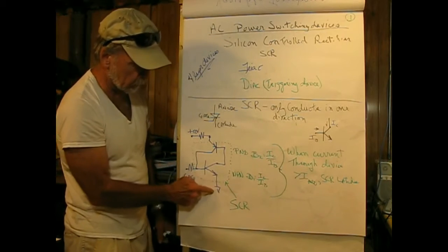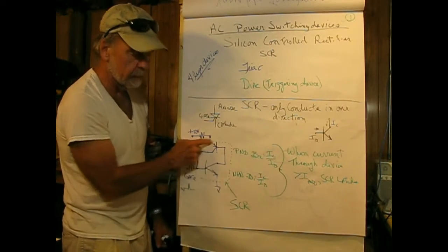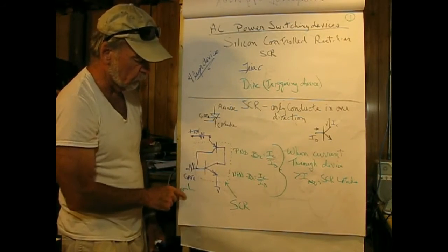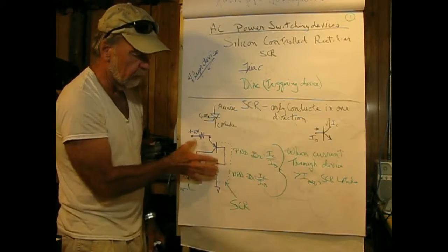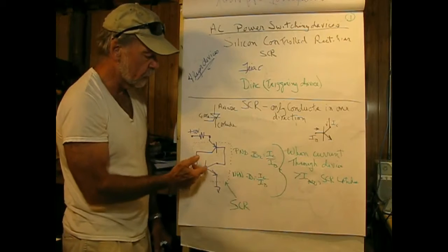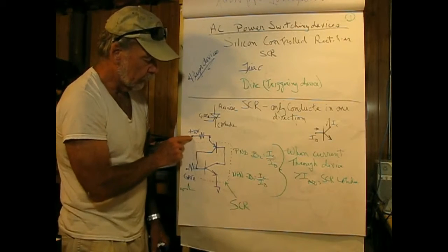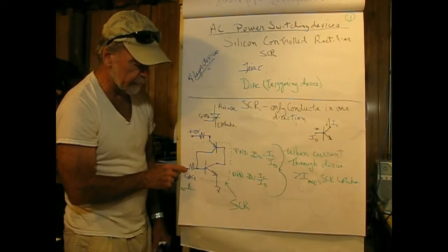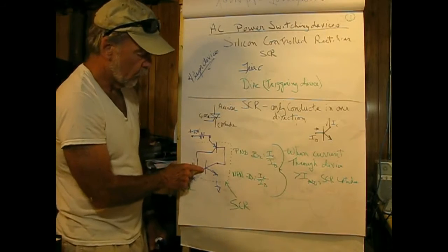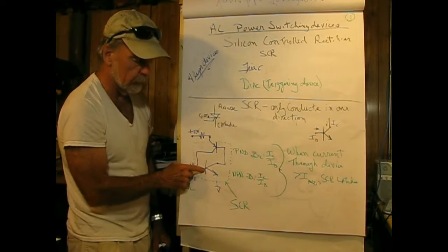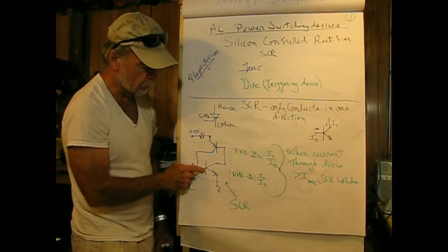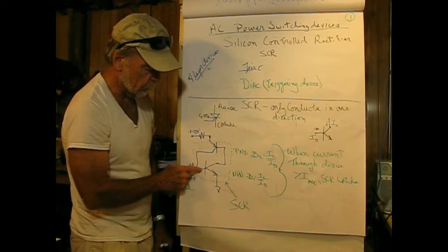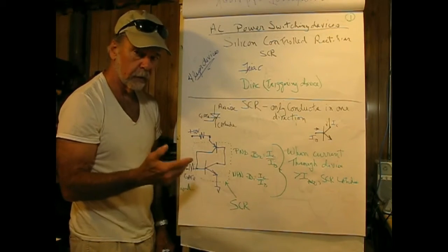So if we have a circuit here with a ground, and inside the dots are the components of an SCR, and we have some load resistor here feeding 12 volts. When we apply power, typically the device will be off. Now, there's a certain exception to that, but it's rather unusual. So what I'm going to do is provide a positive going spike at the gate of this transistor. Now, what happens is that little current flowing into here is amplified by the transistor and produces a collector current flowing in this direction. So the base current flows in, collector current flows in, only the collector current is larger